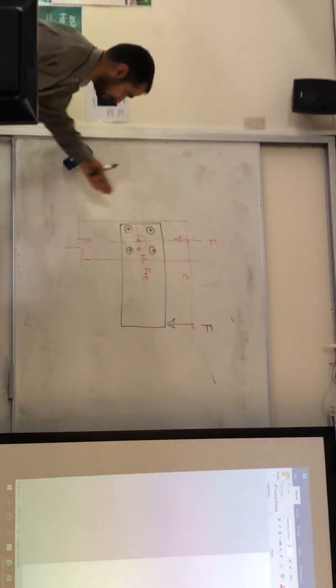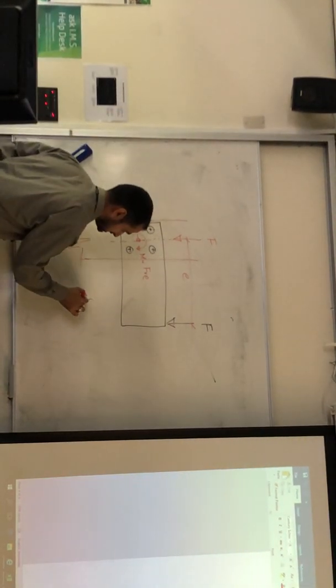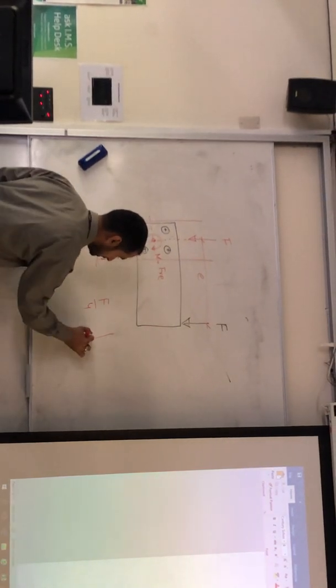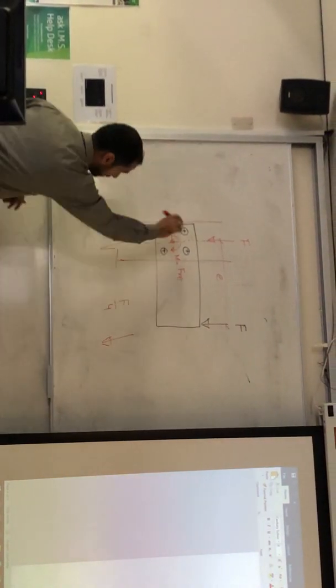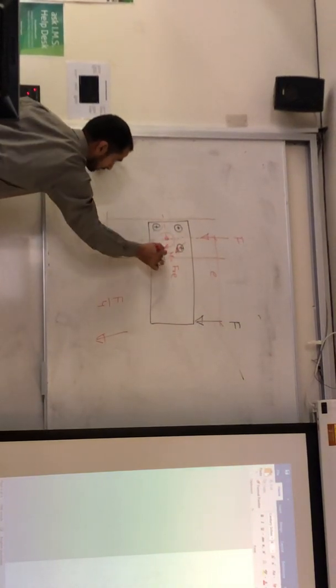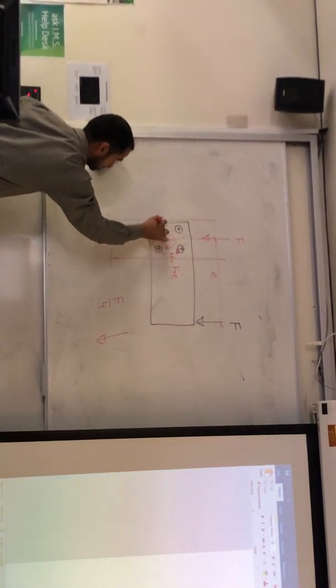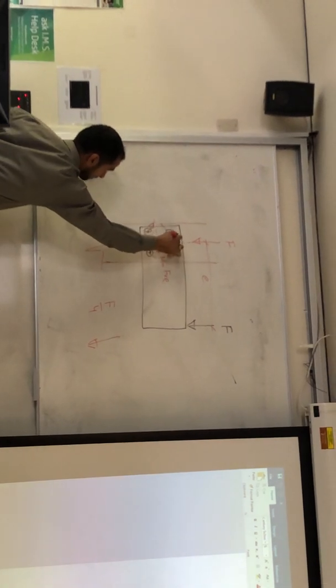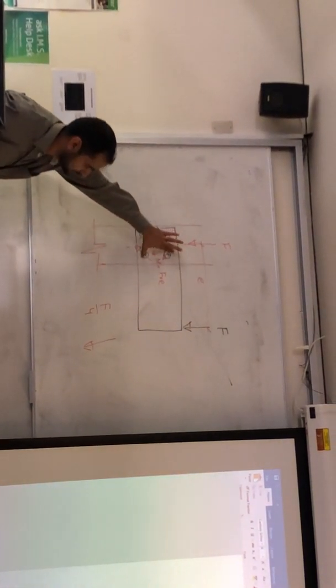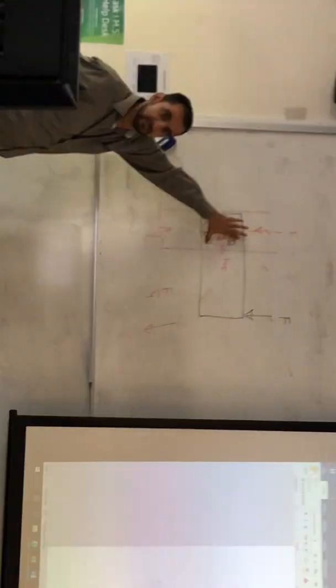From here, it's simple. The normal shear is simply F divided by 4, and it's downward. And then you have the moment force, which will have, let's say it's clockwise. And by inspection, that bolt and this bolt, these two are the worst case.